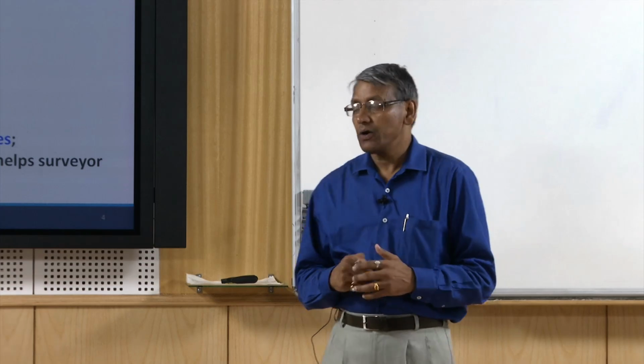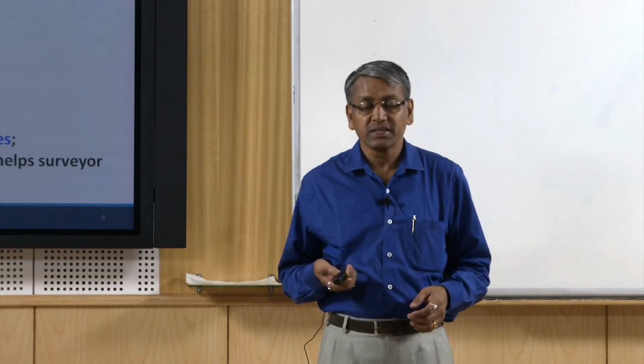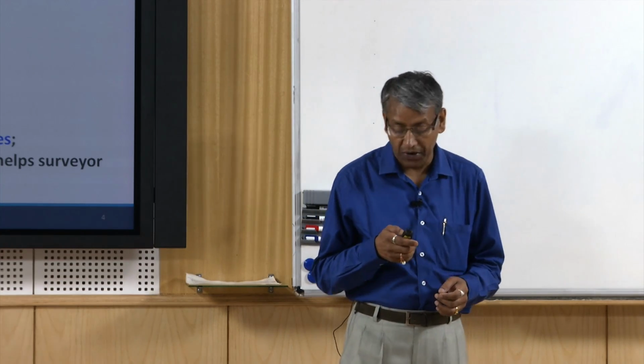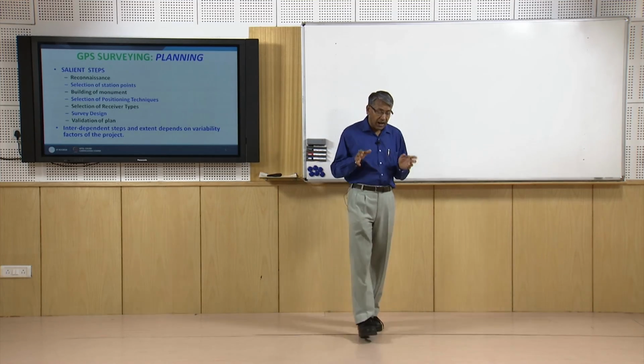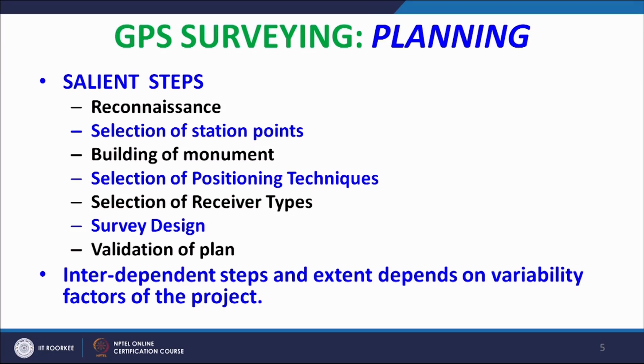Today's class I will be talking on the planning part, and in next classes we will go for other parts of this procedure for GPS surveying. Now the GPS surveying planning starts with reconnaissance, followed by selection of station points.